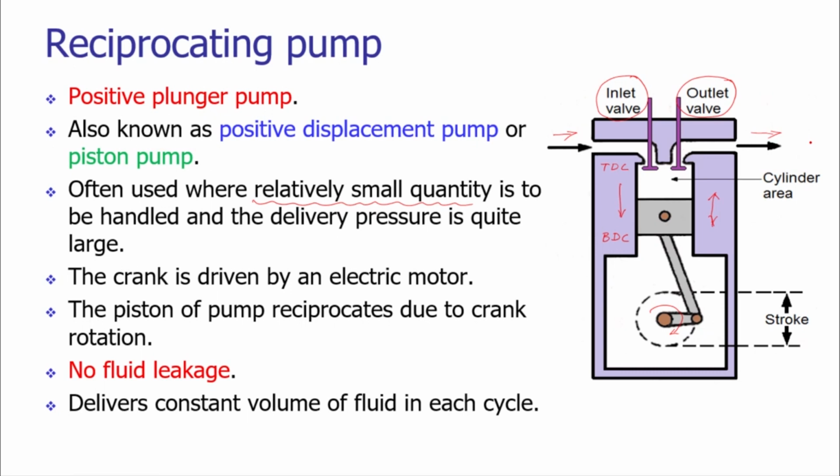The piston cylinder arrangement inside the reciprocating pump has a smaller volume. That's why the quantity of pressurized fluid is less in the reciprocating pump. We cannot have a very large size of reciprocating pump. The construction or manufacturing of such a huge reciprocating pump is difficult.